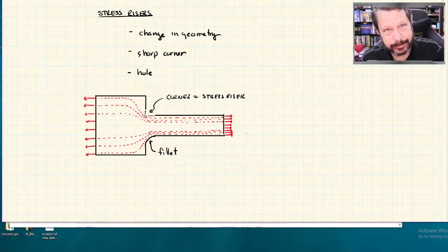So yes, that's why they have that fillet in there, and it's pretty extreme. These fillets don't have to be huge, but they do help. The larger the fillet that you can still have your design do all of its other things, the better.